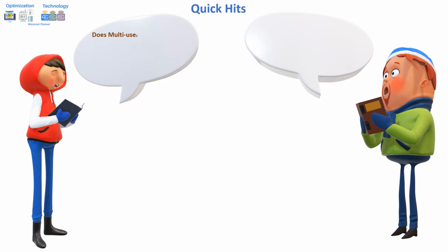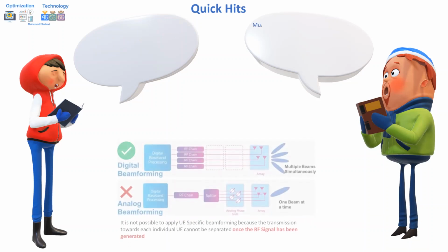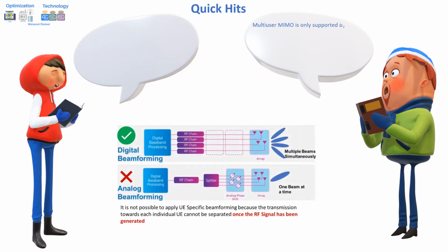Does multi-user MIMO work by both analog and digital beamforming? Multi-user MIMO is only supported by digital beamforming. And this is because analog beamforming can generate only a single beam.